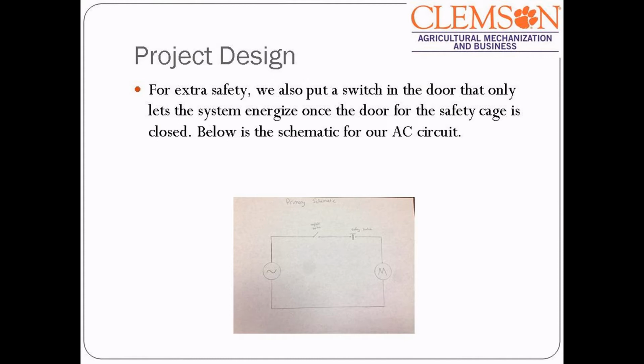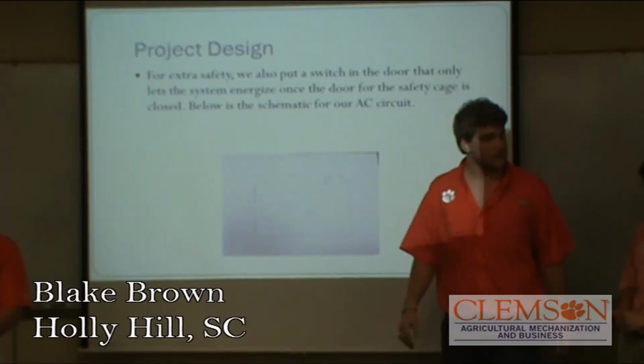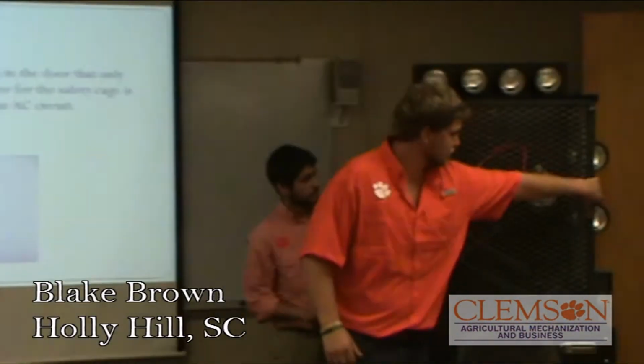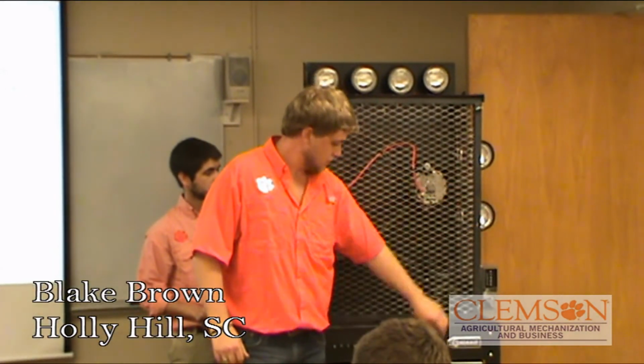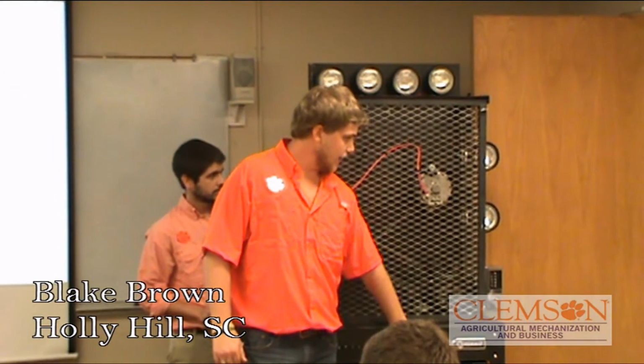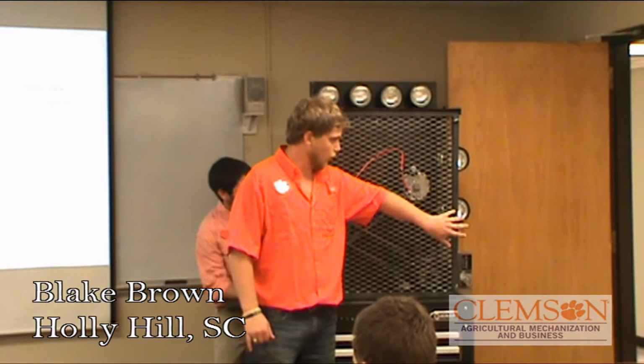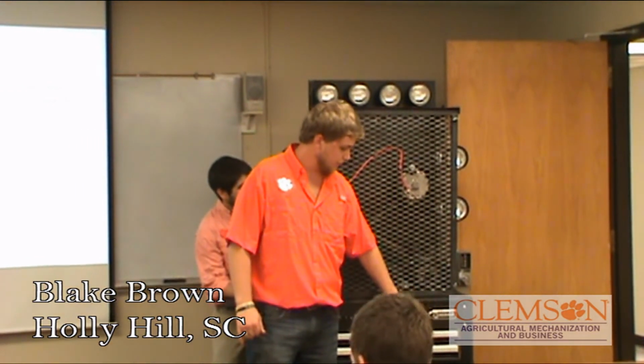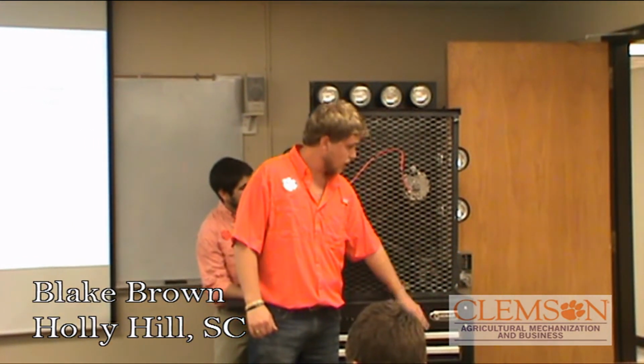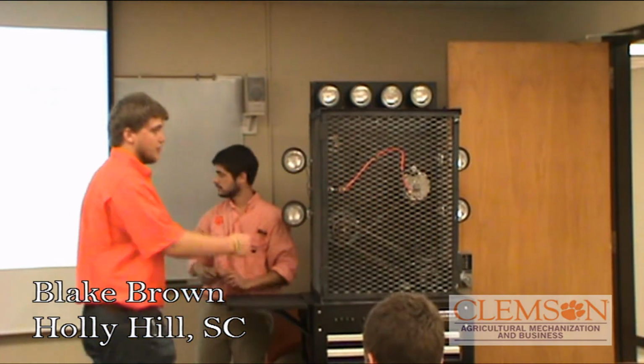We also added a safety switch on the door to be sure no one's hands were in the operation if it got accidentally turned on. You see it's located right here, right behind this door. This is the switch to cut it on, and this kill switch will only enable the power to be directed from the outlet to the motor if this door is shut, or if you put your hand on it.